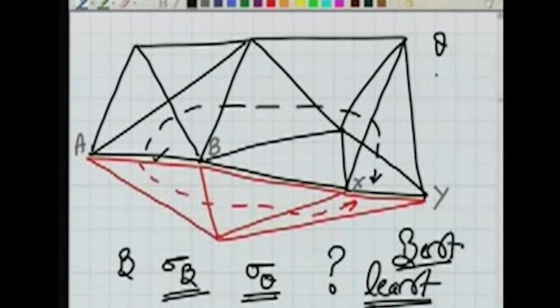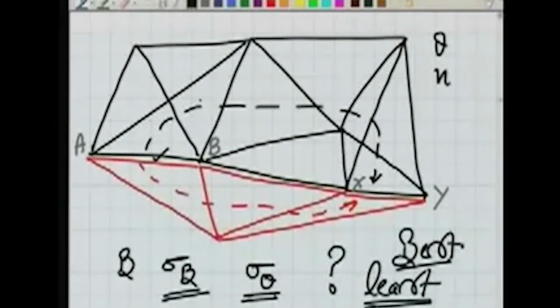So how many triangles are involved in the computation? More important, what is the value of the angle? As I said, all the angles in this black route are well conditioned, while in the red route the angles are not well conditioned. We can see the type of the angles. What is their type? Are they good angles or poor angles? That will also control it.